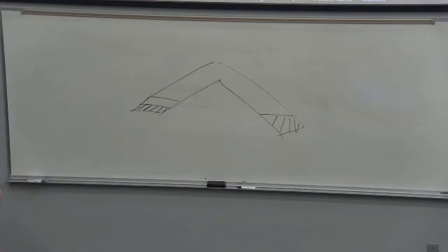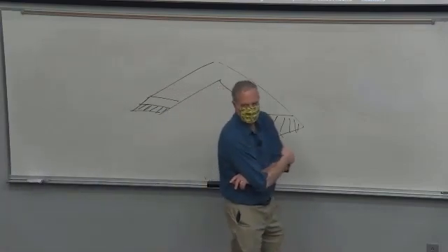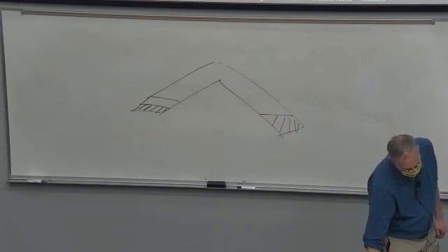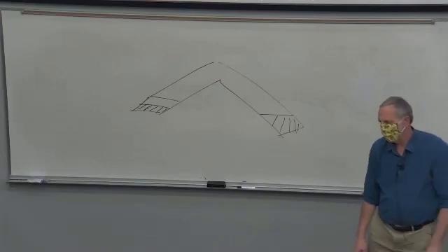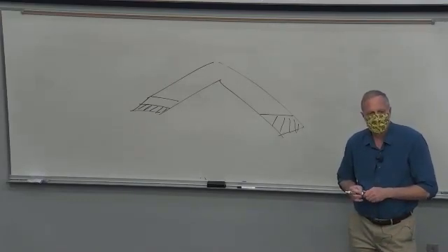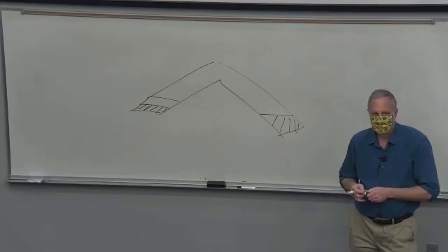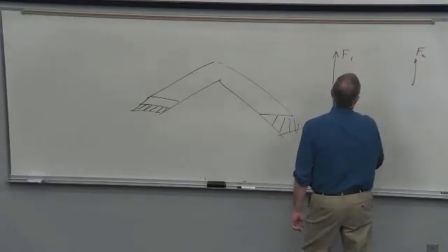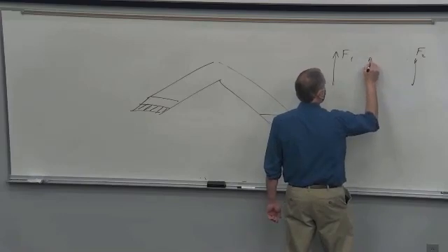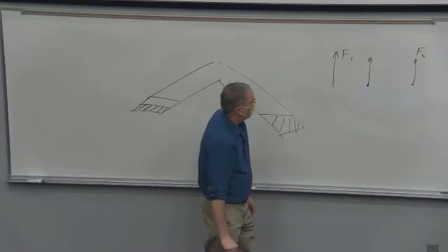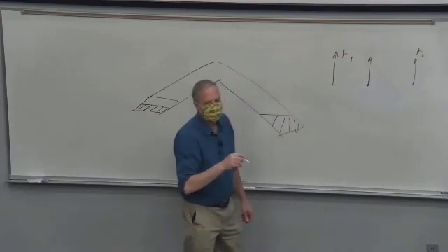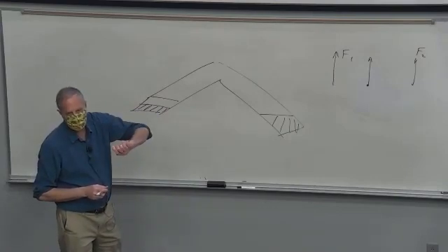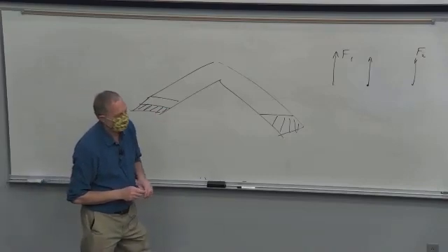The neutral point for what? Yeah, we'll define it. The neutral point is the point where the resultant lift of the tail and the wing act. Right, you have two force vectors. The net resultant, if they're both equal, will act here, right? So the neutral point is just the point where the net lift from both the wing and the tail act. But it will become very important because we will need to calculate where that is to make sure it's behind the CG to get the stability.